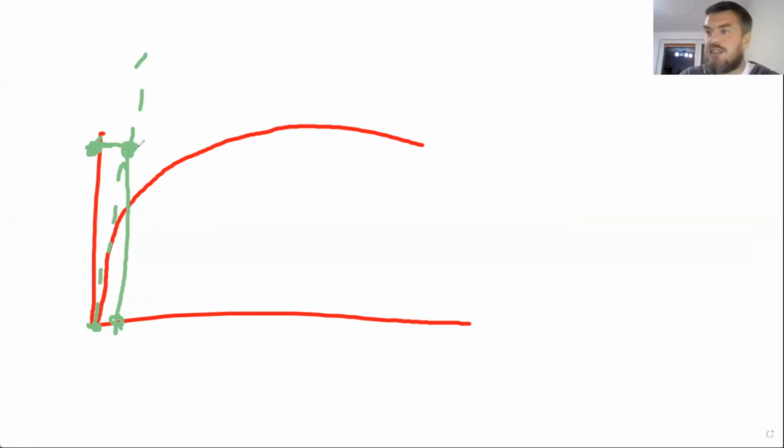Right? And a nonlinear FEA says, hey, wait a sec, that's a stupid outcome, right? Because it knows that I have, for instance, stress higher than yield, and it reduced the stress, and then suddenly the model is not in equilibrium anymore, and so on and so forth, right? So it will say, okay, I will go down here. This is not the load increment I wanted, so I will try to guess again, sometimes parallel to this, sometimes tangent to that. It depends on how you set your Newton-Raphson iterations.